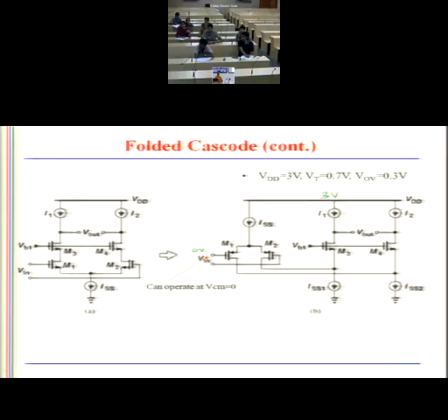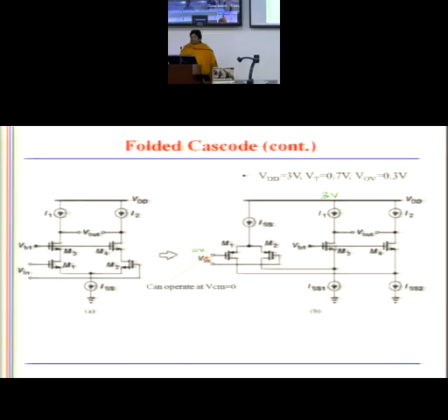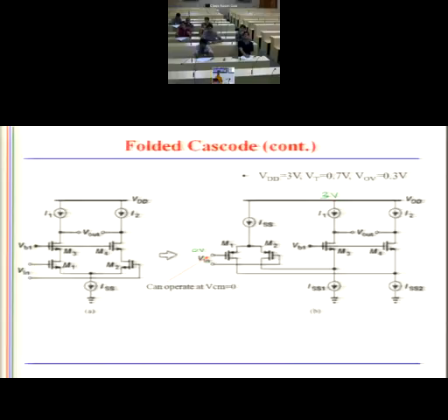1 by gm parallel. No, it will not be 1 by gm. This is NMOS. You are looking at the drain, it is an r0. NMOS. Yes, r0. You have to simply apply the concept of source degeneration. Source degeneration. So it will be no, not 2 gm.